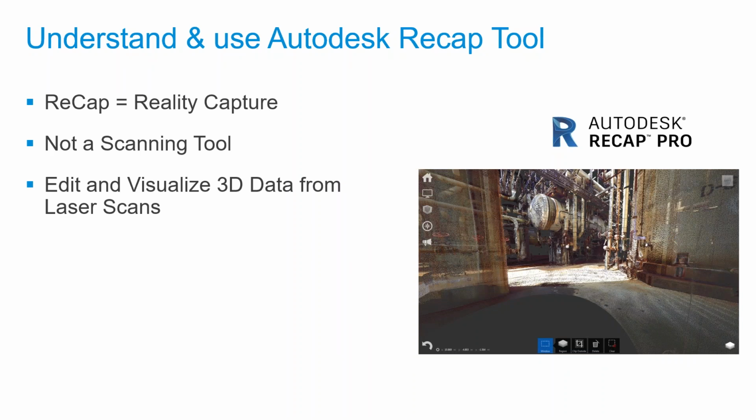As the name suggests, ReCap is nothing but reality capture. Just to make you understand, ReCap is not a scanning tool. What ReCap can do is bring in the scanned information from the laser scanning tools available in the market, whether it is Faro, Leica, or Topcon for that matter, and you could bring those scanned images into ReCap Pro.